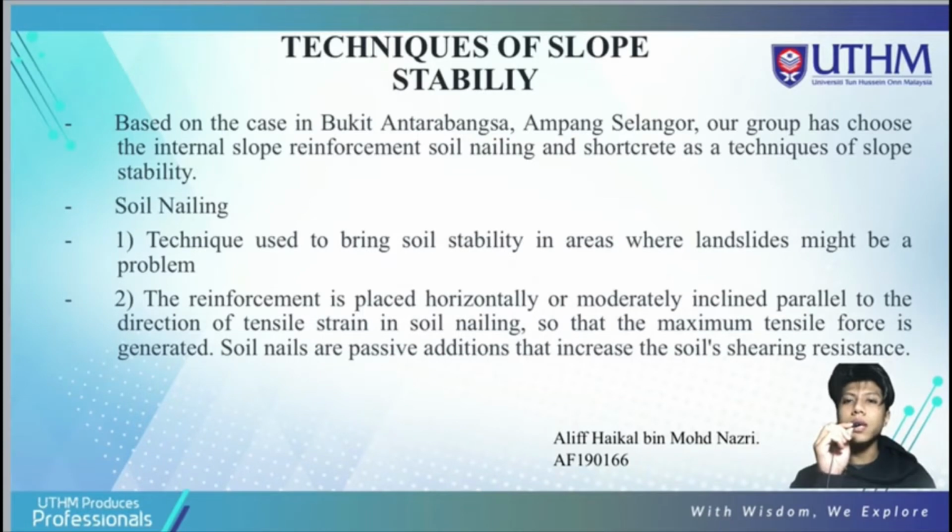As for the concept, the reinforcement is placed horizontally or moderately inclined, parallel to the direction of tensile strain in soil nailing, so that the maximum tensile force is generated. Soil nailing is a passive addition that increases the soil shearing resistance.